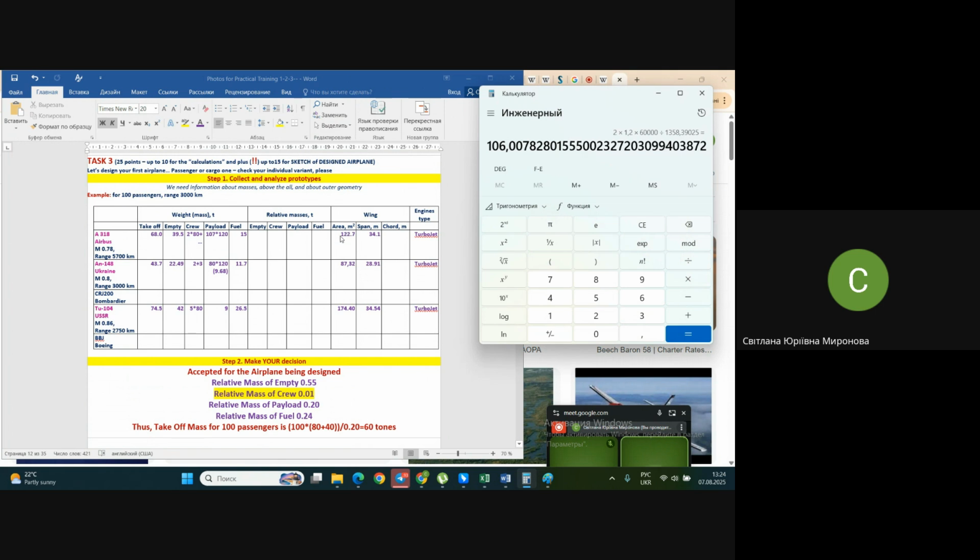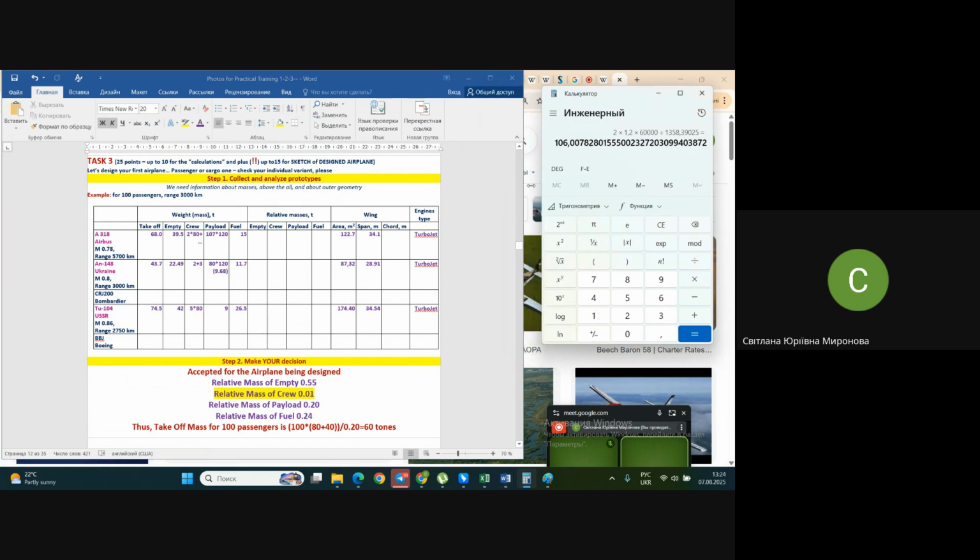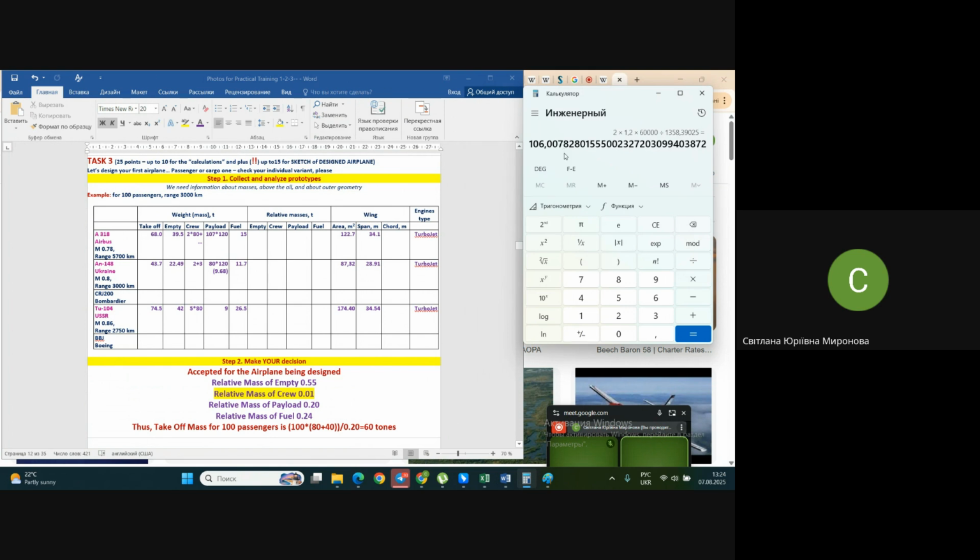Let's use the calculator once again. I already did it, I know the values, but let's see together. Look, area of the wing of the Airbus is 122. Let's take it less so it does not jump permanently. We are calculating maximum takeoff weight to the area: 68 tons to 122.7 square meters. 554, you see. Just remember this value. Antonov, 43.7.